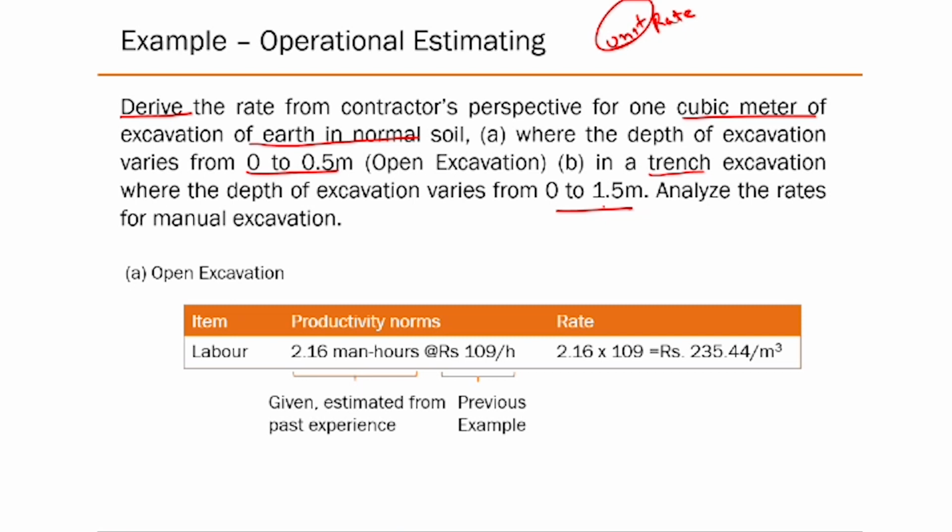What else? Do you know what's the difference between open excavation and trench excavation? Open excavation is slightly less deep, and the ratio of this, perhaps these two, whatever this A by D ratio, is not too slender essentially. So there is no risk of soil caving in, or there is slightly less risk of soil cave-in.